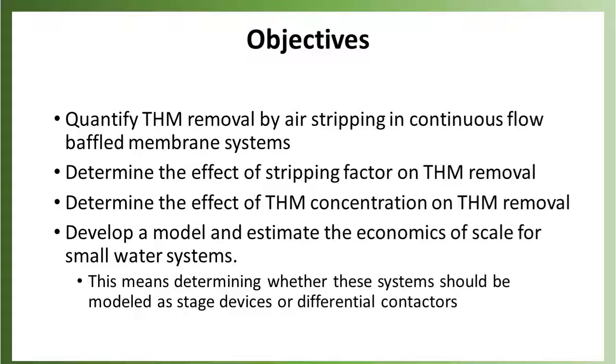So the goals that I've had in my research are to continue Francis's work and to quantify the THM removal in an air stripping system using continuous flow. This is actually an unbaffled membrane, but we want to scale up to baffled membranes, so that's what we'll be looking for eventually. We want to look at the removal efficiency as it relates to stripping factor and to the concentration of trihalomethanes within the system themselves.